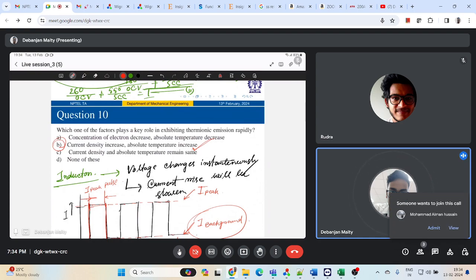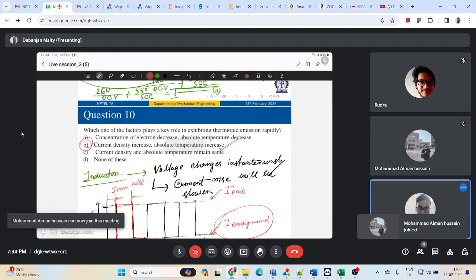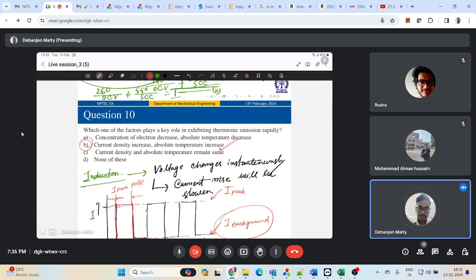The first set, which I am classifying as primary electrons, is emitted by the cathode, and basically carries more heat compared to the secondary electrons. Secondary electrons are produced as a result of the ionization process in the arc gap.